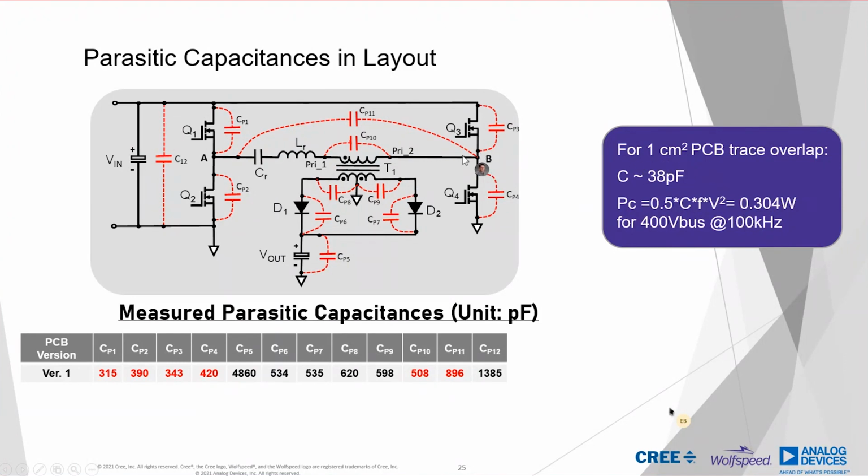So when you consider designing a power board that has big heavy traces for carrying the current, you can end up with areas many times this. And so you need to make sure that they're not overlapping and coupling to planes that they shouldn't be coupling to, both from a noise perspective and from a power loss perspective, because that's just extra loss in your circuit that you need to handle.